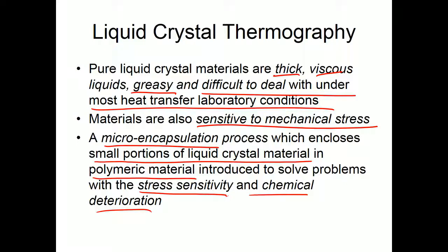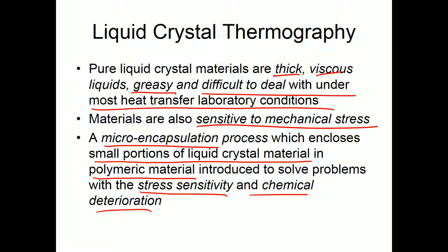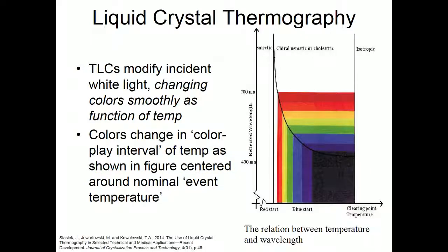So, there has been a lot of work. If you ask any polymer person or chemical engineer, they will show how this encapsulation process actually happens for liquid crystals and how they can be used in common heat transfer applications, because as we say, pure liquid crystals are thick, greasy, viscous fluids which are not very conducive to the measurements that we are dealing with.